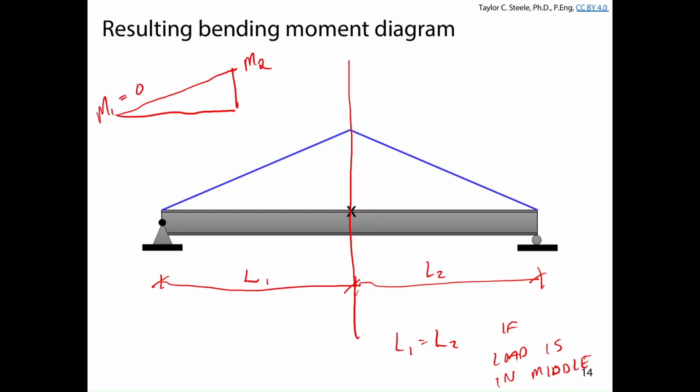And so in this case, we've got an unbraced segment on the left with a value of L equal to L1, and a segment on the right that's also going to have an unbraced segment length of L2. Over here, pretty much the same thing, M2, M1, and L2. So we'd use this value of L. For example, on the left-hand side, we'd use a value of L1 to calculate the critical elastic lateral torsional buckling moment.